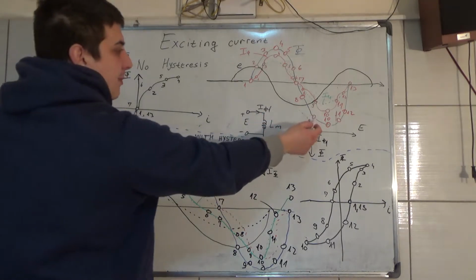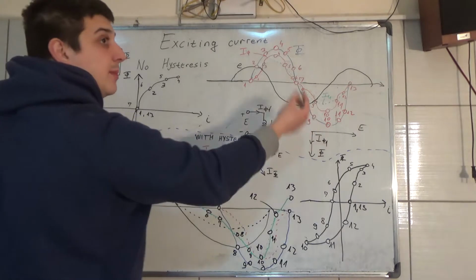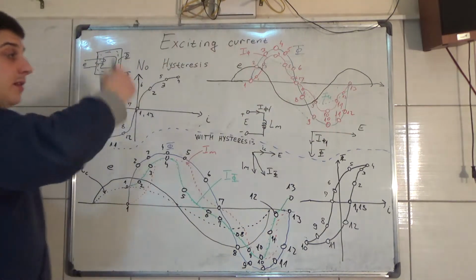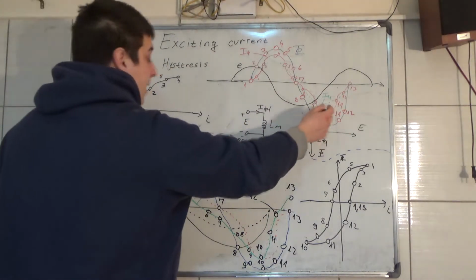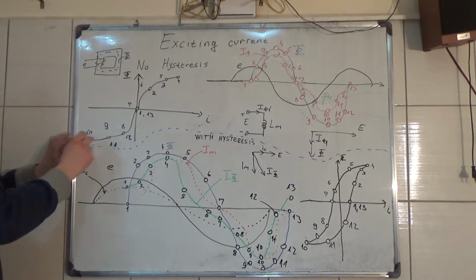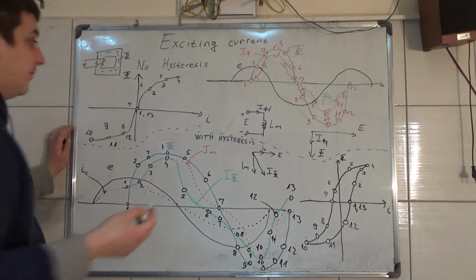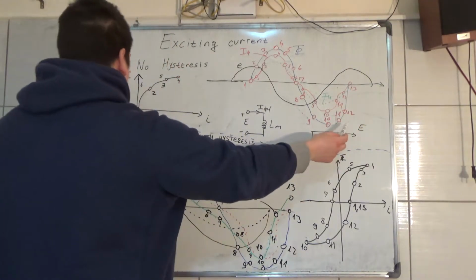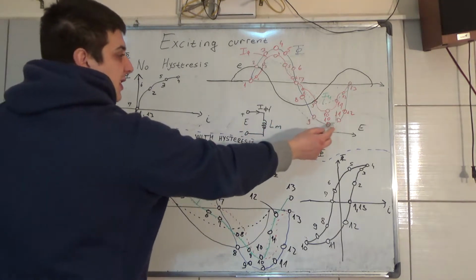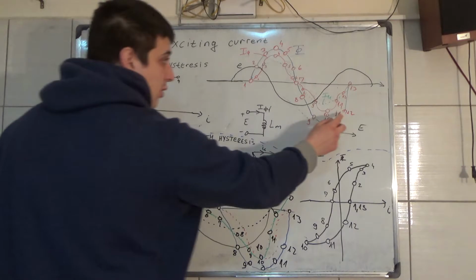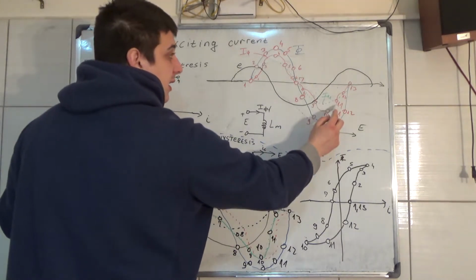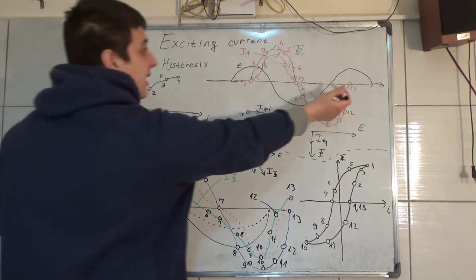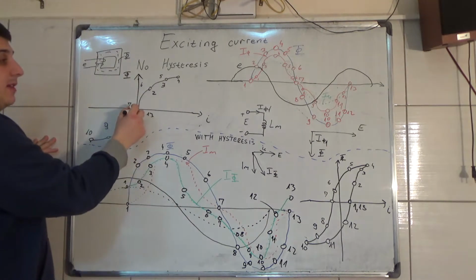Now it goes to number 9, where the magnetic flux increases in the inverse direction. The amplitude in the other, opposite direction is 10 here, and this is the maximum value of the magnetic flux. Now this decreases to 0. We have point 11, which reaches the same amplitude as 9. It goes to number 12, this exciting current, and finally at number 13, when the exciting current is 0, the magnetic flux is 0.